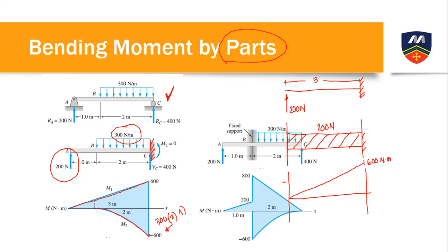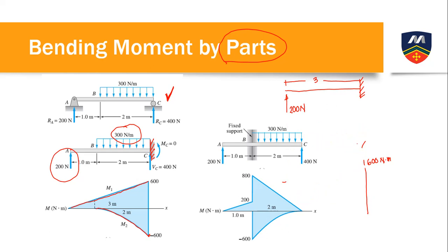Okay, how to check? To see if your moments balance, if you add them, then they should give a 0 moment. Now, again, you can use the cantilever method at any point along the support of the beam. You can do it here at point B, still. Okay, you can cantilever there. So, you take them one by one. So, how are you going to compute the moment of 200 Newton?